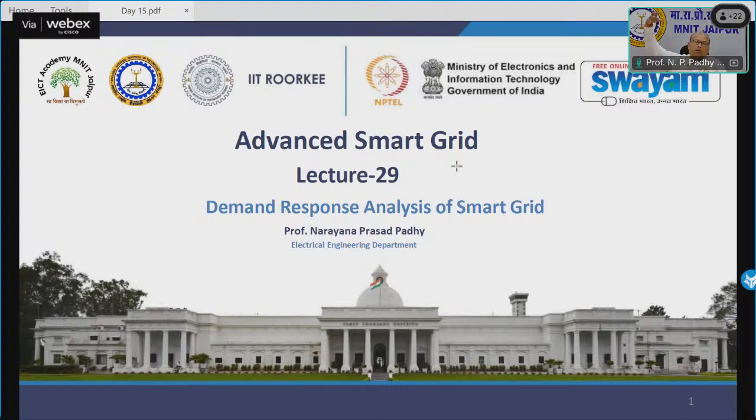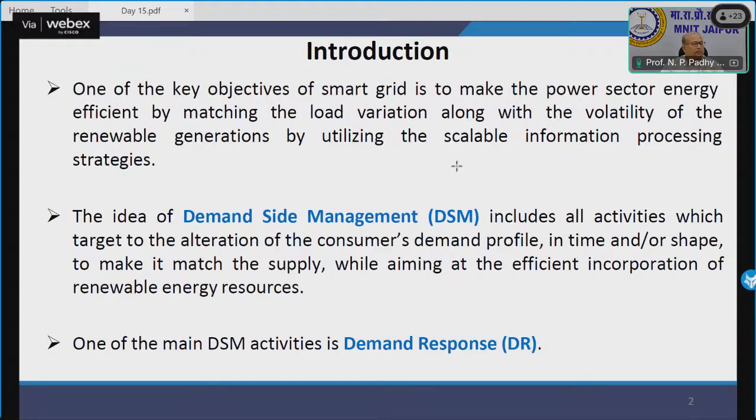The information is not coming only from the utility to shift you from one point to other so that the peak can be reduced. It is otherwise also, we also participate in a manner so that the national peak is moving from one point to other. So the first program which is coming from utility side is more or less known as demand side management program. However, when the consumers participate in peak shifting as well as load shifting programs, then it is known as demand response program. Okay. So, demand response includes demand side management basically.